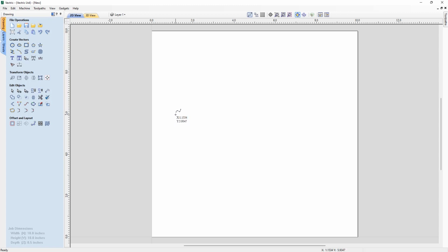So the way this works is you click and that will create a line, and then when you click next, once we click after this point, it's going to turn that into a curve. You can see it's now like a Bezier here. And then here we can click again. So it's very similar to the Polyline tool, except rather than creating straight points, we're actually able to create curved points like so. If you didn't like a span you just created, you can always press the backspace key to undo that, like so.